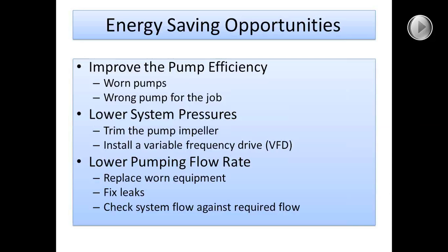We looked at pump curves yesterday. They were operating at lower flow rates, higher pressures, and the efficiencies were really bad. And so they're actually going to replace those pumps and put in new pumps that are designed to operate at the flows and pressures they're operating at, at the best efficiency point of the pump. The other thing you'll run into, a pump may have been designed to run hand lines and wheel lines, and they've replaced the hand lines and wheel lines with center pivots. And so the operating conditions are a lot different than it was originally designed for, and there may be energy savings opportunities there. It's just the wrong pump for the job.